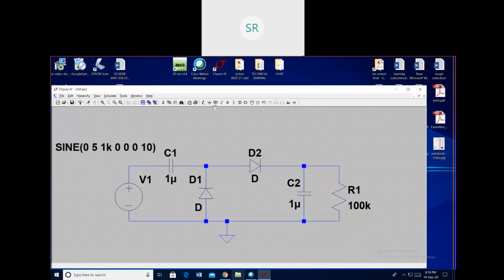Now you can add a label. This is important. Without a label, later on you can't see where the readings you are taking are, which current reading or which voltage readings you are observing. So better use labels here. I'll click on this label and I'll get a text window to type the name for the label. I've written Vi and the type of this port is input. Select input and click OK. Place it here.